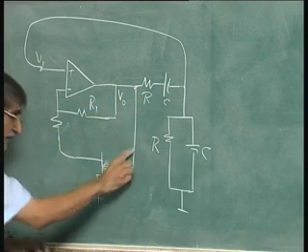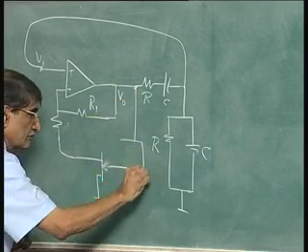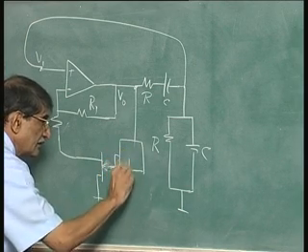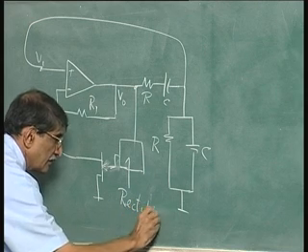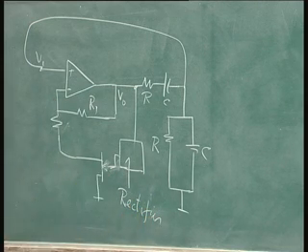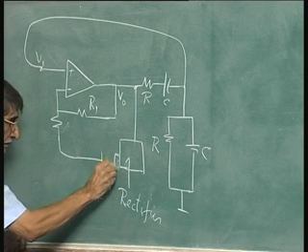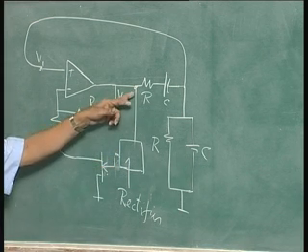In fact, you must have a rectifier in between here, because to give input to this gate, this should be DC, and what you get here is AC.